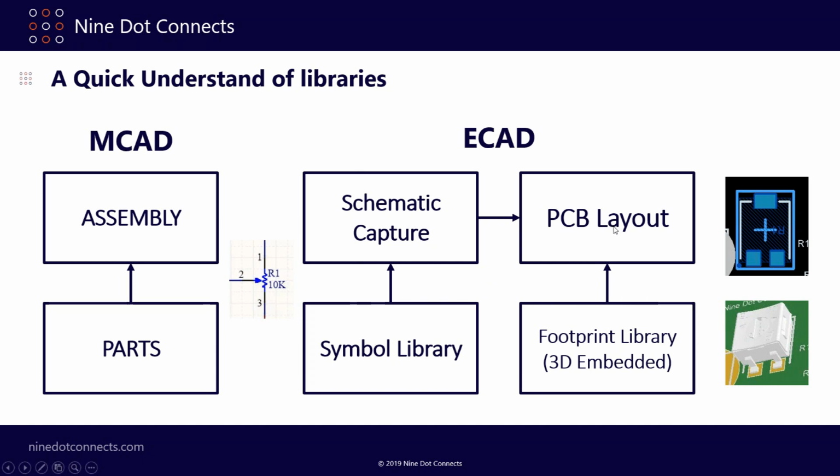So in the PCB layout, we can't use the symbol library. We actually have to create another library, and that's called the footprint library. And in SOLIDWORKS PCB in particular, we show both the 2D representation. So this is where it's supposed to sit on the board. It's copper representation. And we can also do its 3D representation. And this capability right here is what allows us to eventually communicate with SOLIDWORKS CAD. That's the cool part about this here.